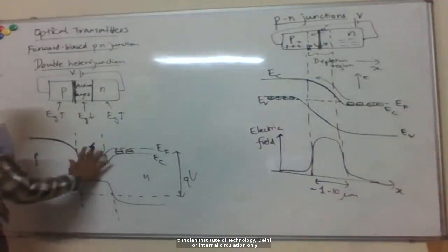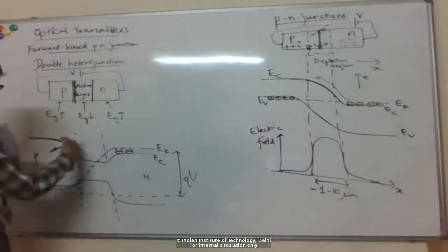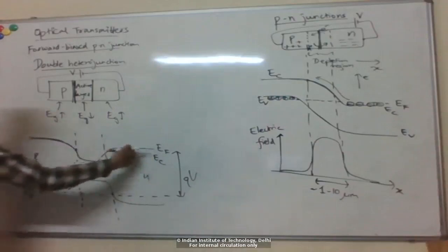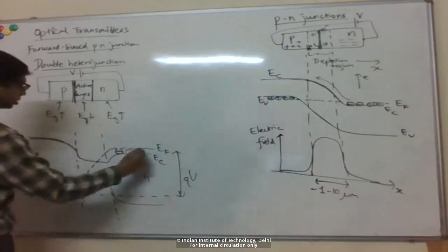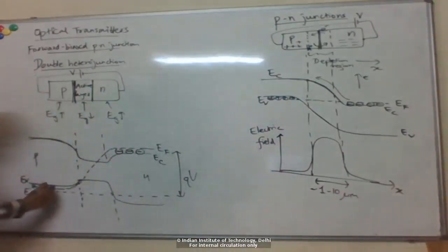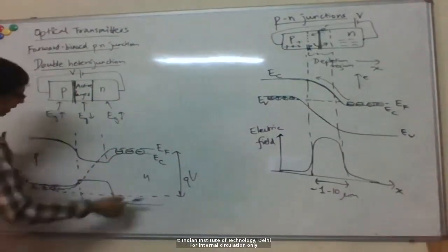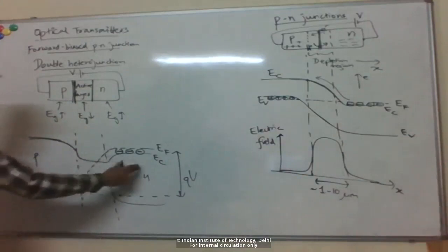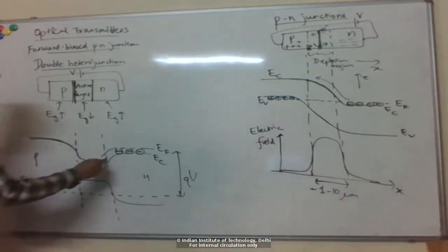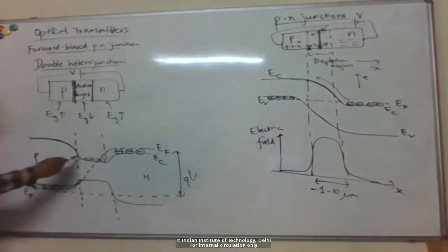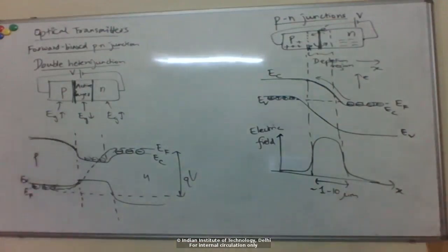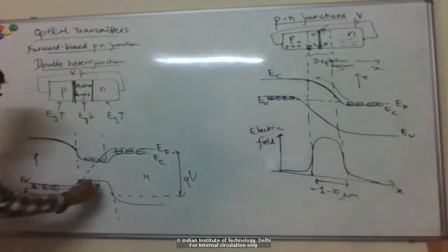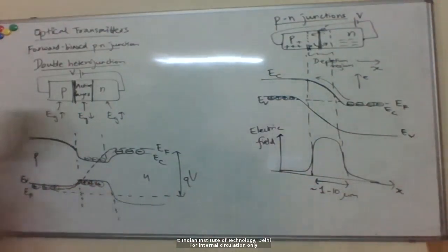So when we didn't have this active layer in the middle, what we saw was, okay, this barrier from N to P was lowered and the electrons will just flow like that, right? Similarly, holes here, right? They just flow like that. But now suddenly there is a region where the band gap is lower than these surrounding regions. So when the electrons come here, they actually end up at a lower energy, right? And now they see some sort of barrier to go into the P region. Okay. Similarly, holes when they come here, they see some sort of barrier to go into the N region.